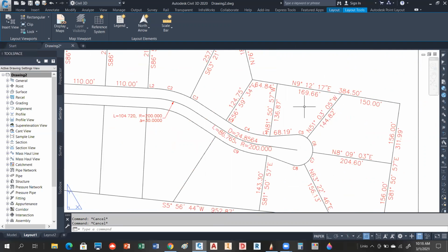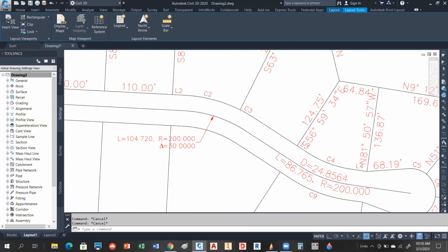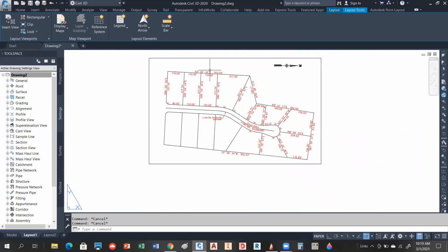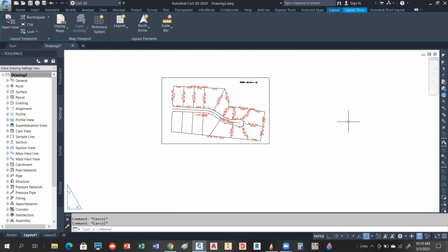I think the sheet that I did with you guys was at 0.10, which is what we're going to knock these down to. You can notice the tags here. I think that's a 0.1 height and that's a 0.15 height. So depending on your scale factors and whatnot, you have to change that. We could change the labels through the label style stuff very easily. And then you could generate another viewport for your tables, and they'll come in also. But the tables are a little bit harder to place. That's the one thing about them.